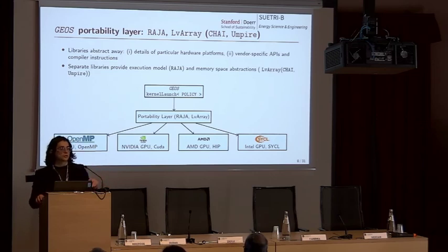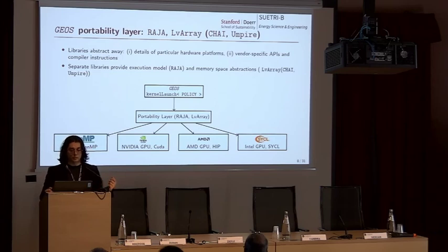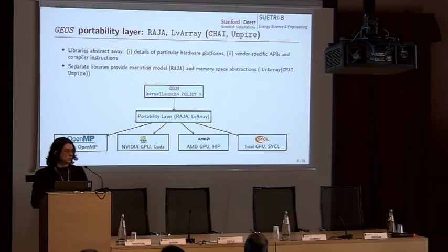For those that are familiar with discretization of PDEs, normally you want to start with a notion of a vector, right? And then when you think of large-scale simulators, this vector needs to be distributed. So LvArray is that abstraction that allows you to code without thinking that you need to distribute. And the natural extension is to create a matrix, and therefore the matrix is already distributed. So this portability layer is quite important.